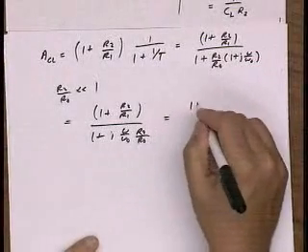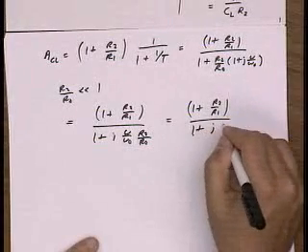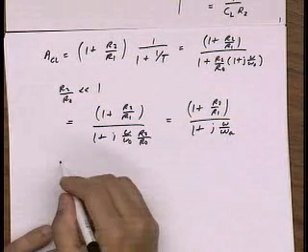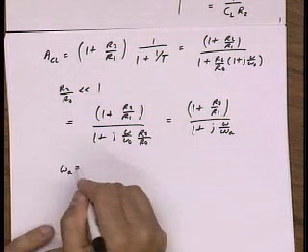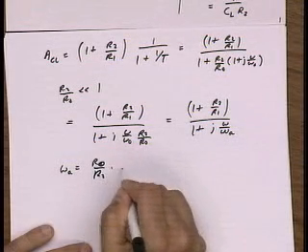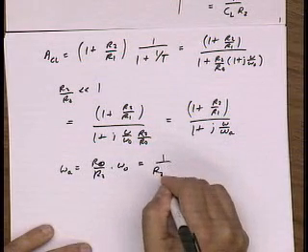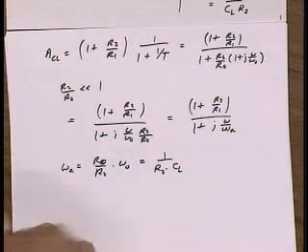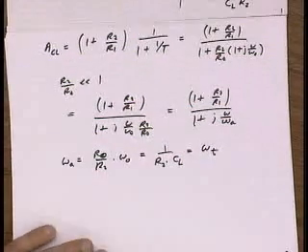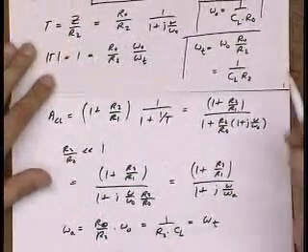And I can write this as the DC gain plus the 3 dB bandwidth of the amplifier, omega A. And so omega A is R0 over R2 times omega naught, or 1 over R2 times CL, which is in fact the unity gain frequency that we just previously calculated, omega t.